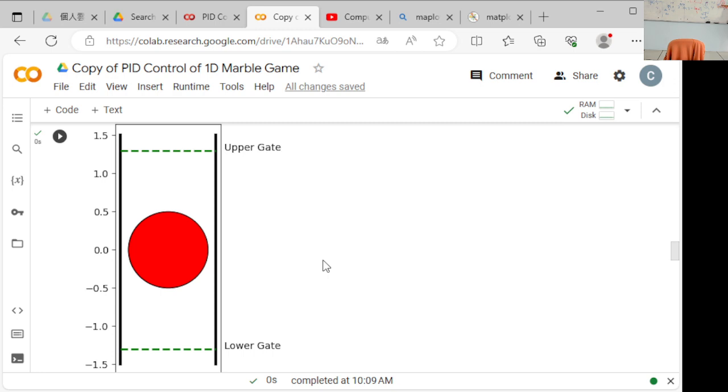And by using that time, we can estimate what the velocity was, which then allows us to modify our control to make sure that we turn it off before we reach our zero location here, or before we reach the upper gate location. That piece of information is crucial in order to do the control properly. Otherwise, your ball is going to oscillate, start slowly, and then just go wilder and wilder. Eventually, you have unbounded oscillation, destroying your apparatus or shooting out of the apparatus.